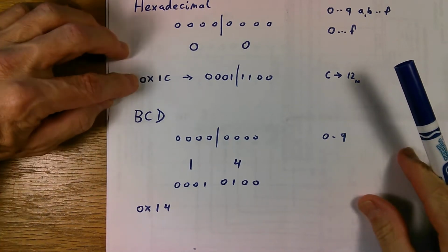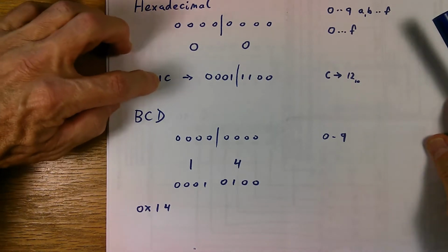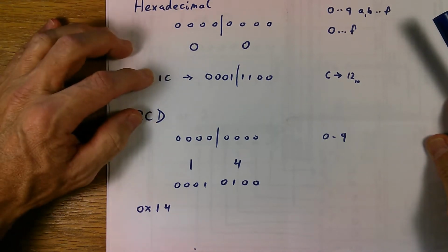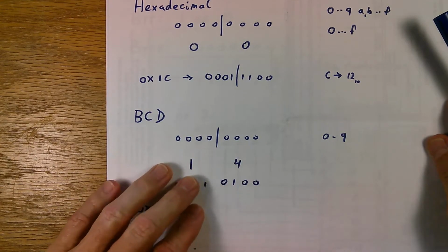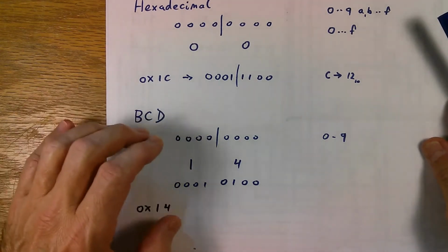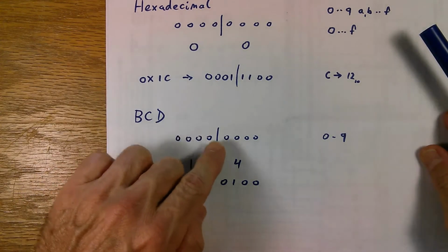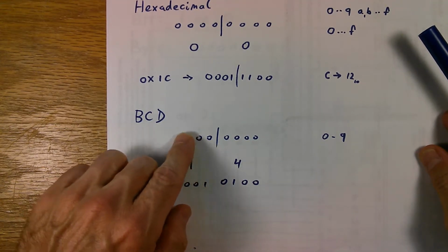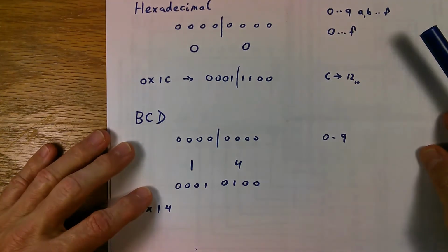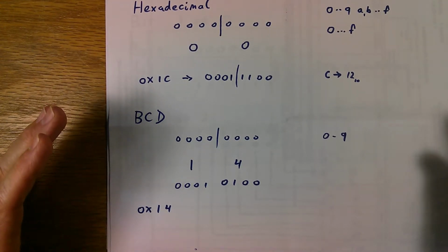And when you write that down for your compiler in your code, you prefix it with a 0x, and then you follow it with the digits in hexadecimal. I also talked about binary coded decimal. That one you have to manufacture. The compiler doesn't do that automatically for you. But what you do is you still divide it up into groups of 4 bits, but you constrain the combinations of the 4 bits to be 0 through 9 only, and the upper 6, A through F, don't occur.